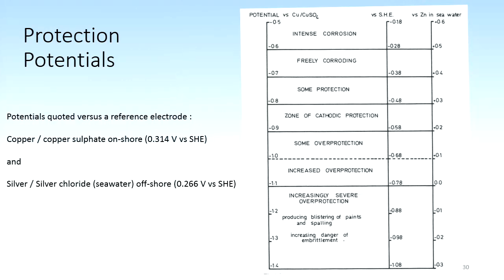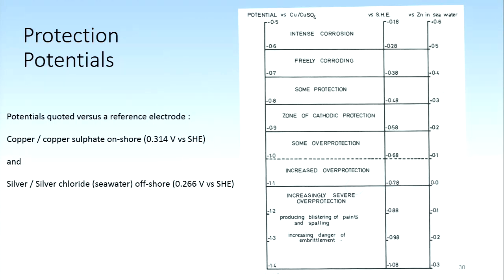You were saying regarding the applications, onshore, offshore. Which one is onshore impressed? So, buried pipes onshore usually impressed current, offshore usually sacrificial anodes. Just because the conductivity of the seawater is so much higher, and you don't have a load of electrical problems of trying to get a power supply unit out in the middle of an offshore oil well or something like that.